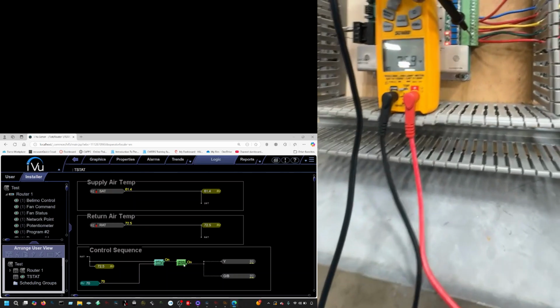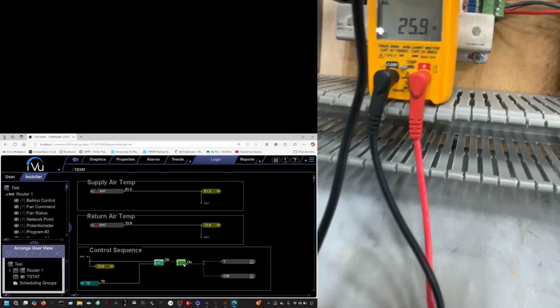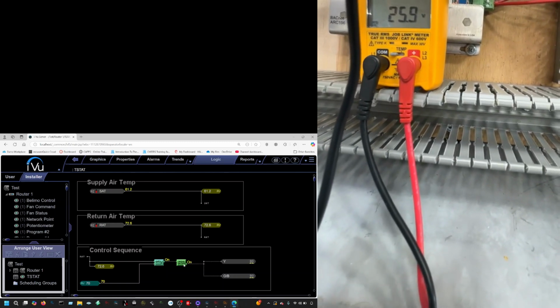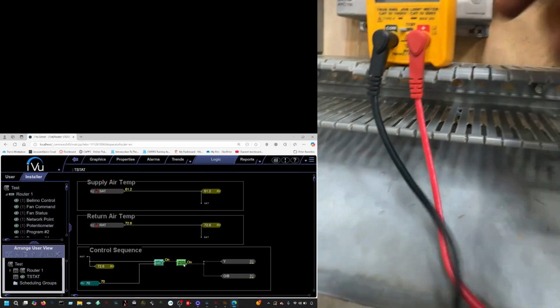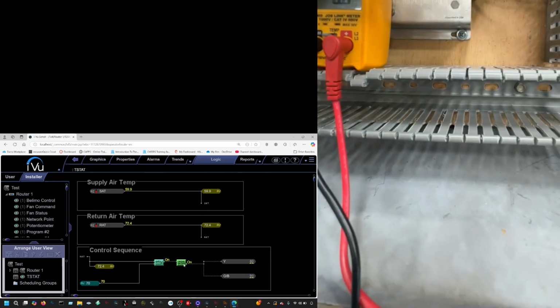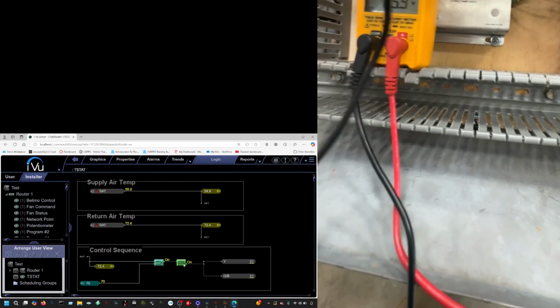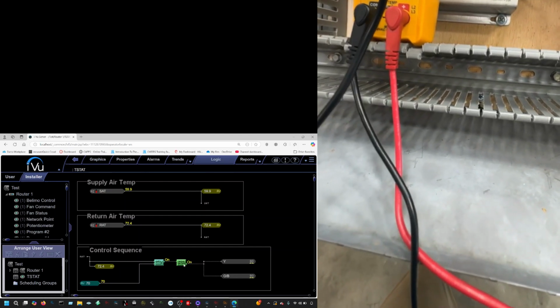You see, 24 volts. So my binary output 1, it's true. It did close between 2 and 3. See if I can go this way a bit. It did close between 2 and 3 because I'm reading 24 volts from common or my ground to 3.